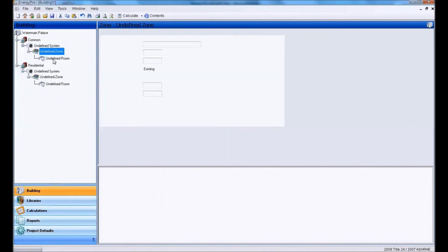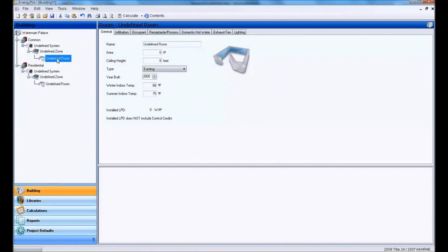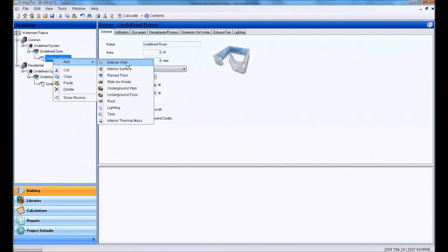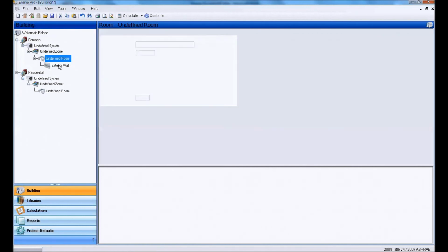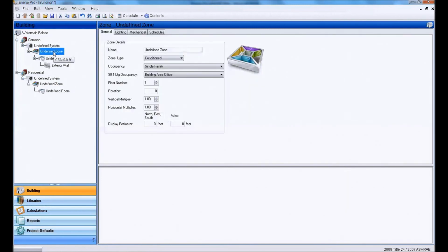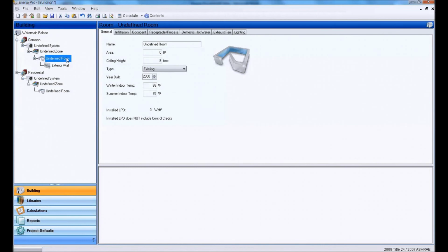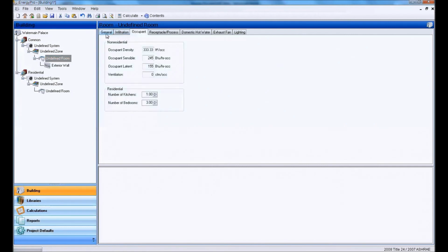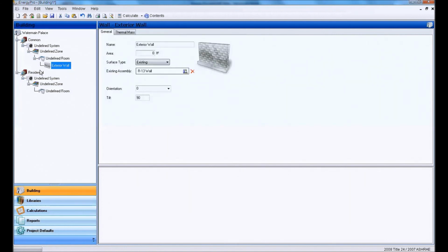Okay, so I'm in my rooms now. And I'm going to build in exterior walls, and these exterior walls are each elevation. So this is my floor level 1, and this is a block load and not a room by room, but each block load should have a good representation of the amount of kitchens and bedrooms. And so each wall again represents each elevation, so I should have four walls, and each wall should have a window.